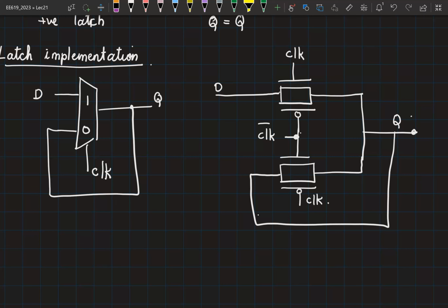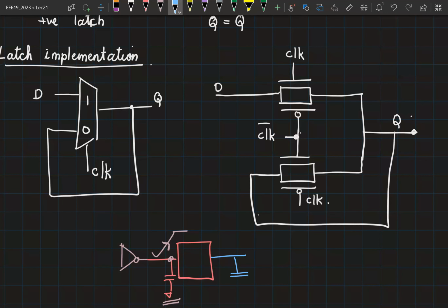Okay, so if this is a circuit that you have designed, if you know what is the input capacitance your circuit is offering, and if you know what is being driven here, you will know the estimate of the rise time and fall time, right? So either you have to give the information about the input capacitance, or you make a table saying that if the rise time here is so much, and if the load that my circuit is seeing is so much, then the delay is this much.